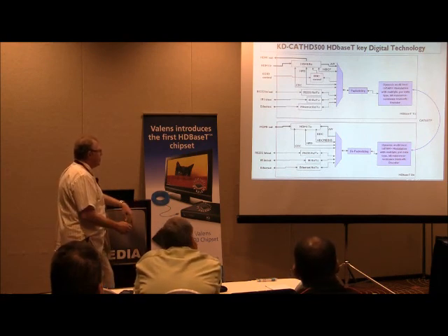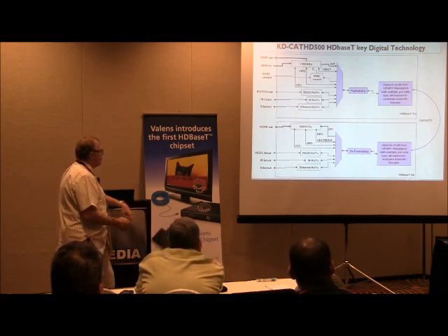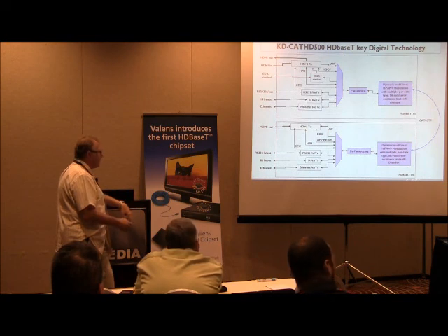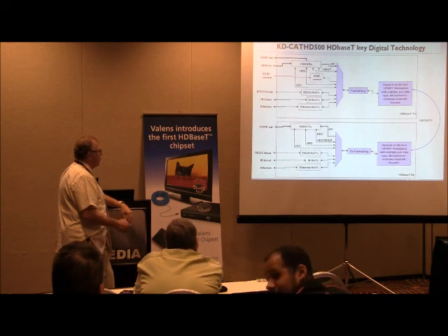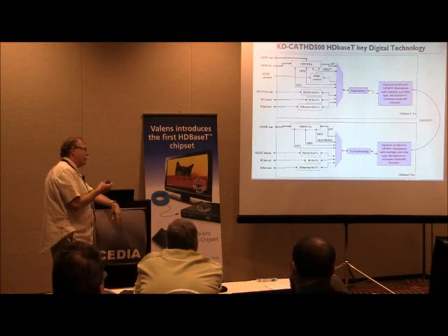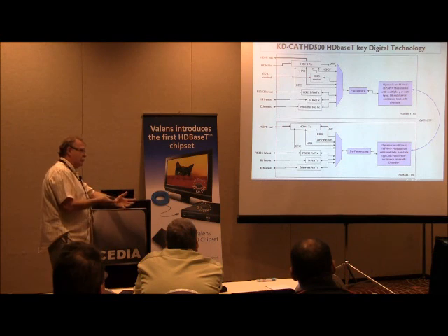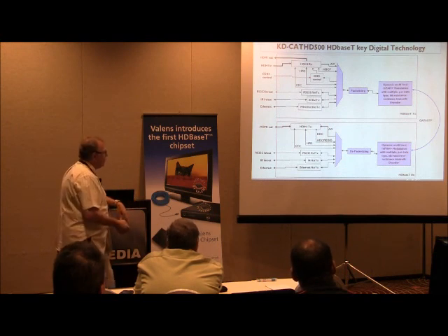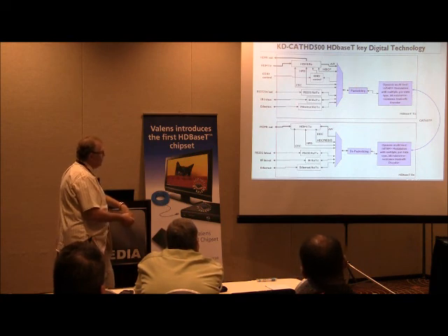The data is decoded into digital data from HDMI TMDS, reclocked, cleaned up, and mixed in with many other types of data, because the data capability of HDBaseT is much greater than the data capability of the TMDS method. And because data capability is greater, much more data can be added into the mix. 232, IR, and also Ethernet are all transmitted on this single Cat5.